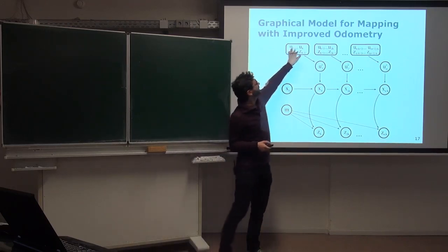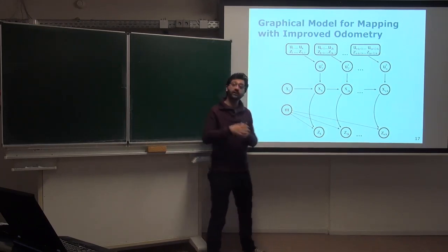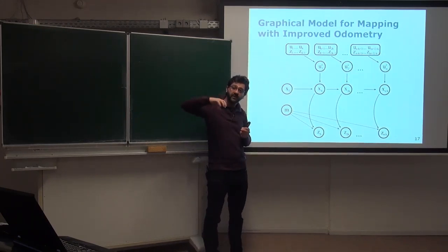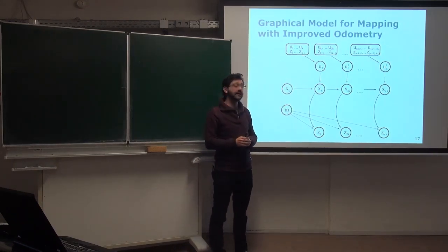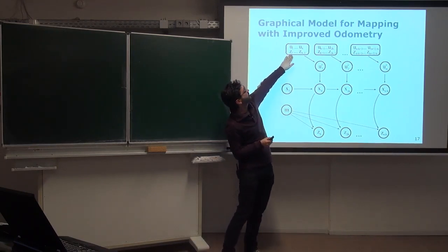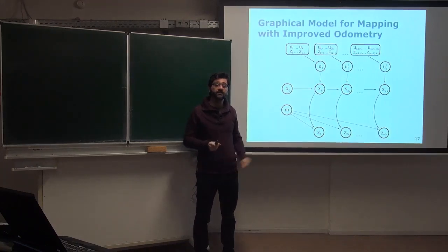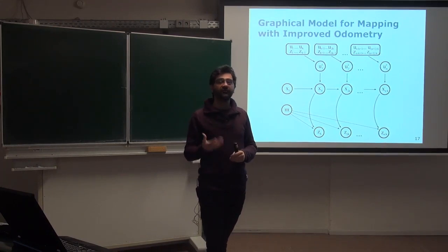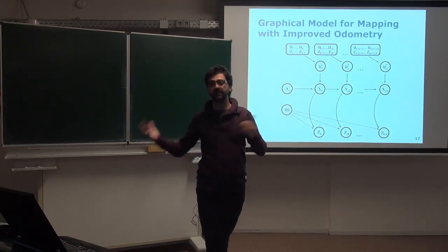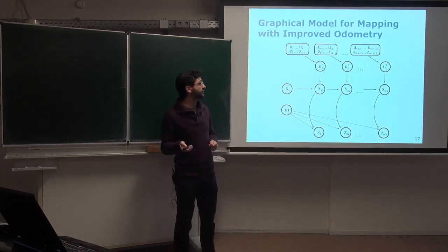So we use k small odometry motions. Up to k minus 1, we improve the estimate locally with the scan matcher, and then in the next step we just use a small increment of the last odometry, and this basically reduces the drift from time step 1 to time step k minus 1. Okay, so that's the idea. And by doing this, we can reduce the number of particles. We can have few enough particles that we can maintain all the maps in memory, and we can get better results for the FastSLAM algorithm.